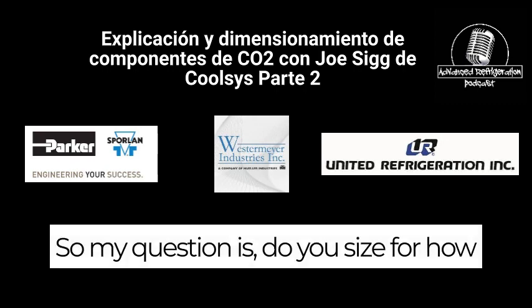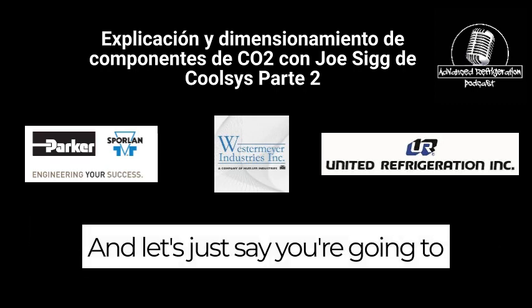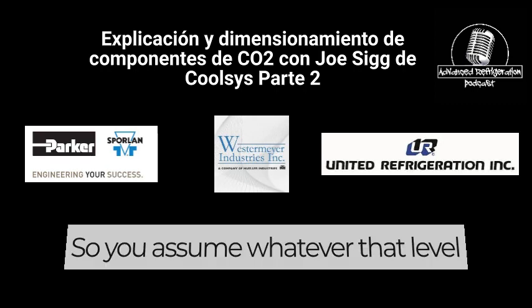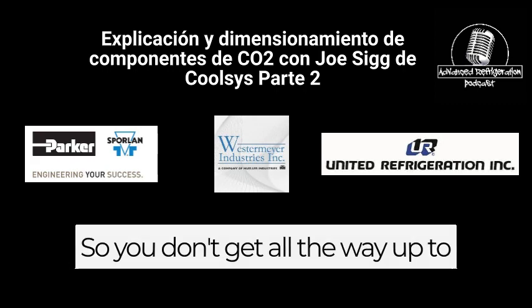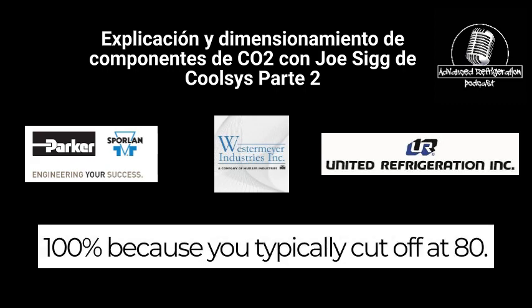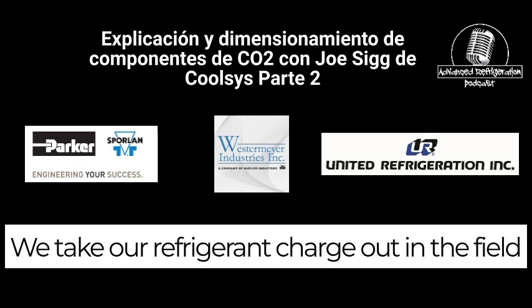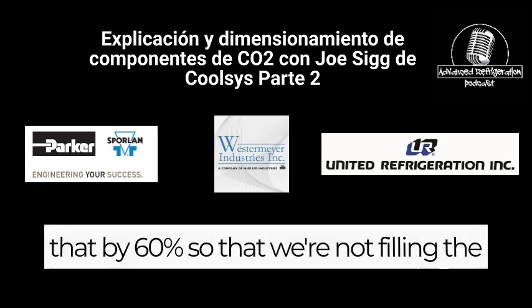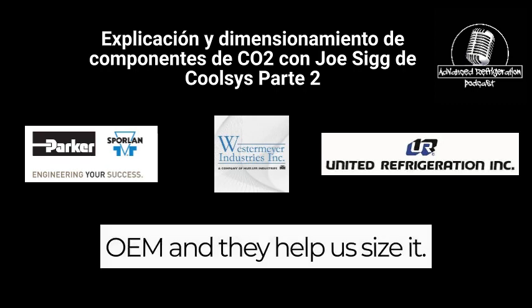So my question is, do you size for how much refrigerant you have out in the line size, and let's just say you're going to maintain a 20% flash tank level? Yep. Okay. So you assume whatever that level is plus that's how high. You don't get all the way up to 100% because you typically cut off at 80. Real simply, we take our refrigerant charge out in the field piping, take 25% of that, and then we multiply that by 60% so that we're not filling the receiver, basically. We're filling the flash tank. And that's what we tell the OEM, and they help us size it, basically. All right.